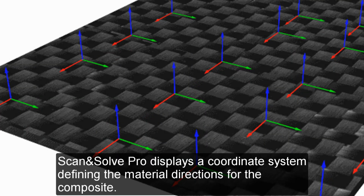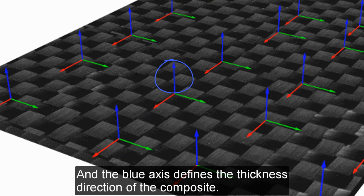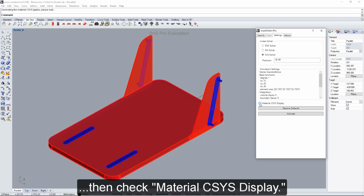Scan&Solve Pro displays a coordinate system defining the material directions for the composite. The red axis defines the fiber direction. The green axis defines the perpendicular direction to the fibers, and the blue axis defines the thickness direction of the composite. To display the coordinate system on the model, go to Settings, then check Material CSYS Display.